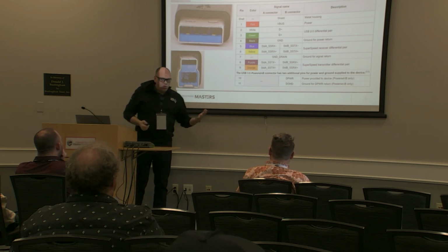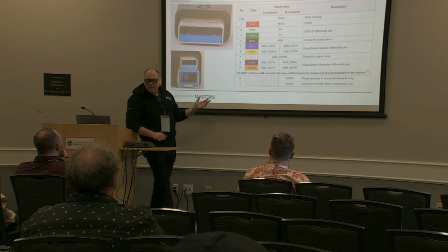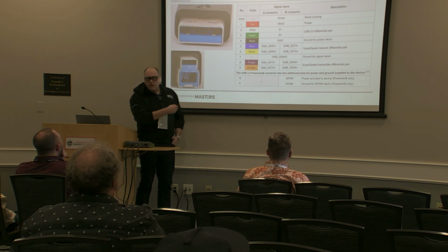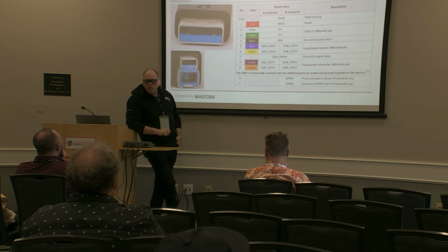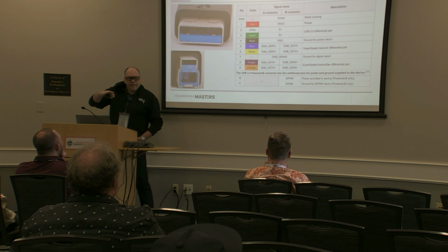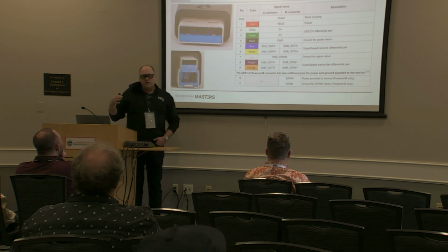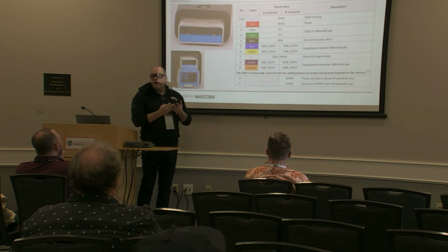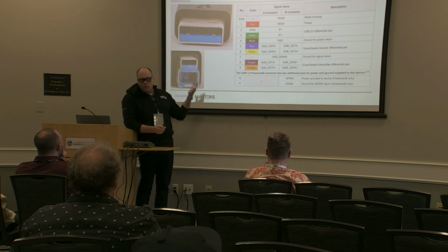So what is important to know about this, and I know this may seem a bit pedantic, and I apologize for that, but I want to make sure and draw attention. This is a USB 3.0 spec, but look here. So when you connect a USB 2 device to a USB 3 port, will it work? Yeah, because those pins are just carried in. So that's your basic USB data path, right? And it is carried forward into the USB 3. It's the same pins. So when you connect it, they marry right up, and so it'll work. So you could even just throw an adapter onto this cable and it would work.